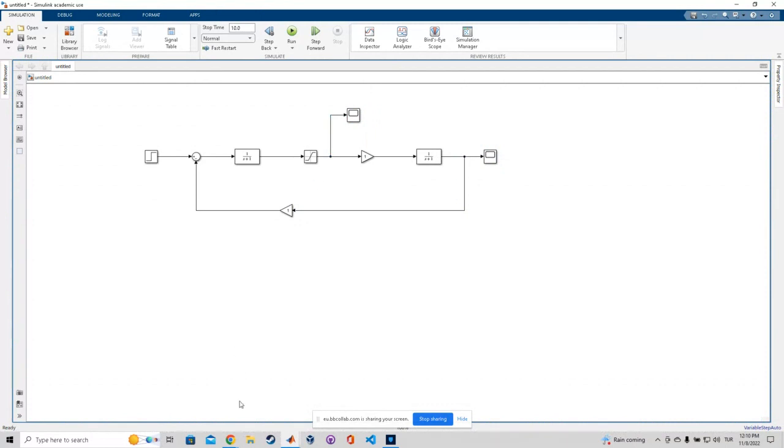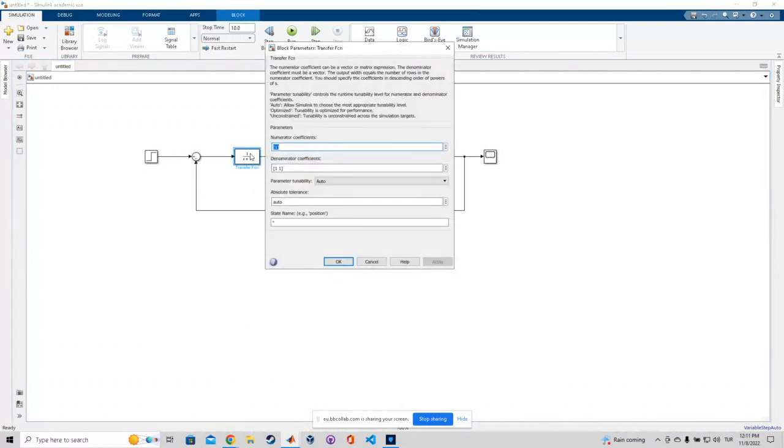Yeah, so in our model, we have parameters that I shared in the file on Euler. You can check it later. So our first transfer function is 1 over LA S plus RA. So your resistive load and your inductive load: the numerator will be 1, and your denominator will change.